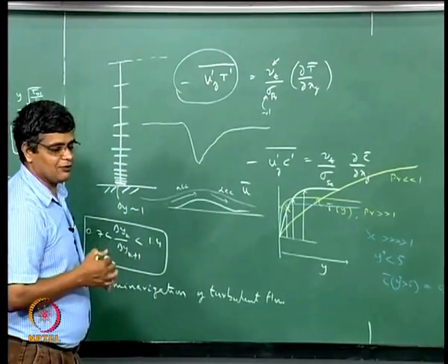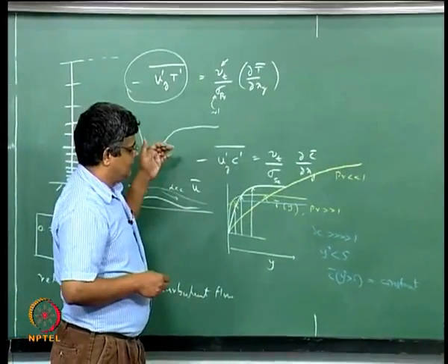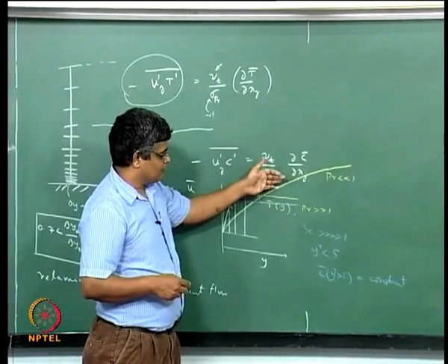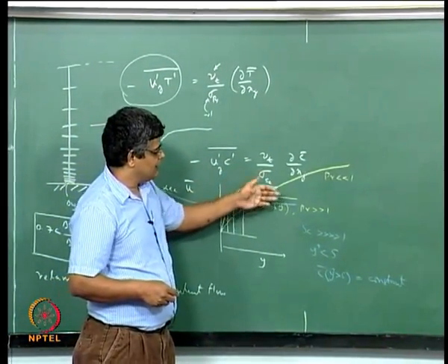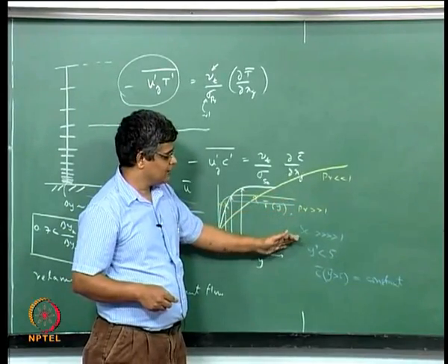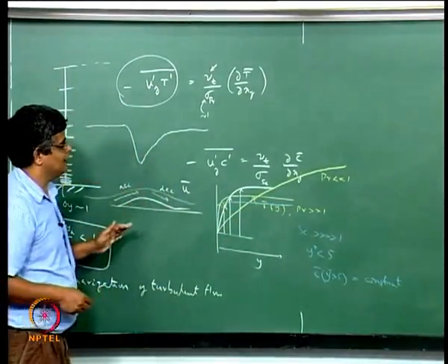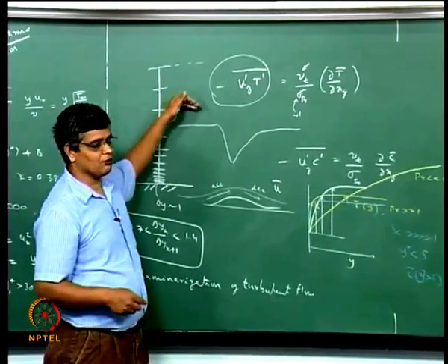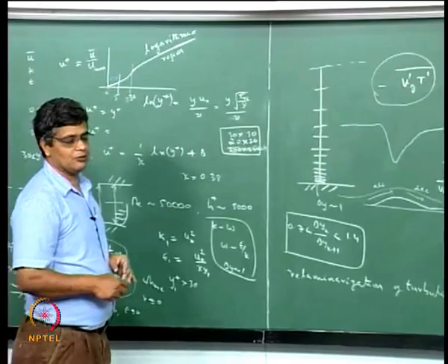One has to be careful about evaluation of the temperature profiles and the concentration profiles for fluids which have a Prandtl number or a Schmidt number much greater than 1. One has to pay special attention to the near wall treatment of these quantities in turbulent flows.